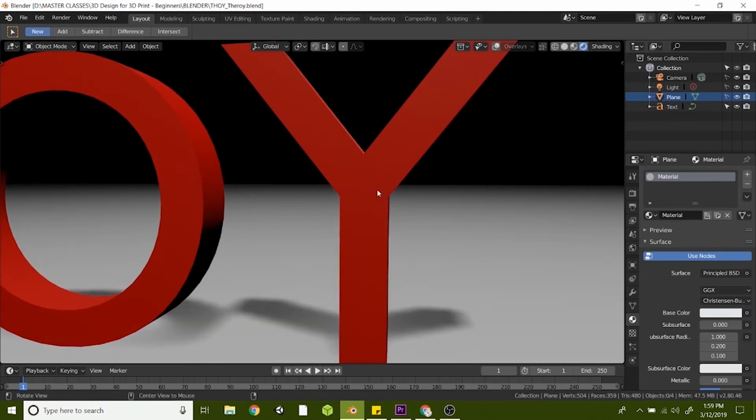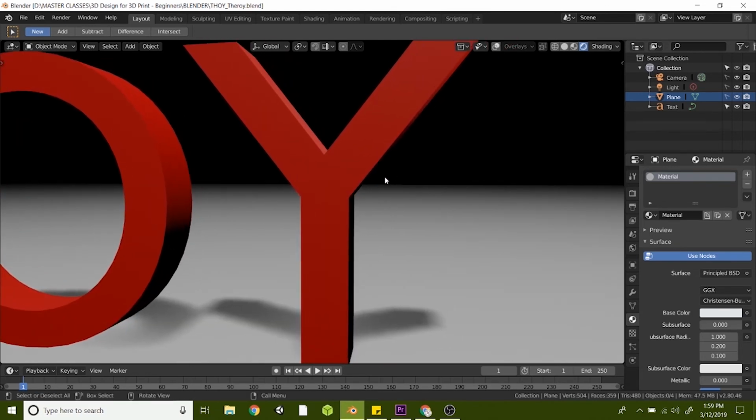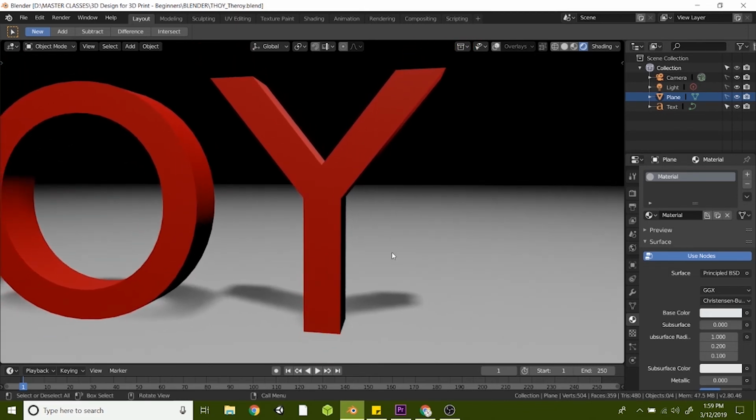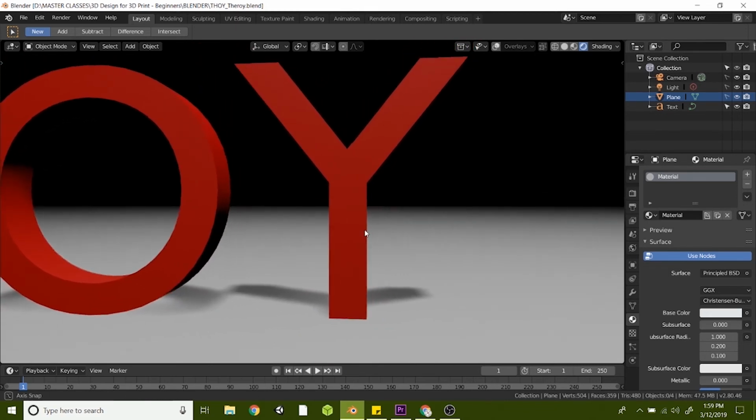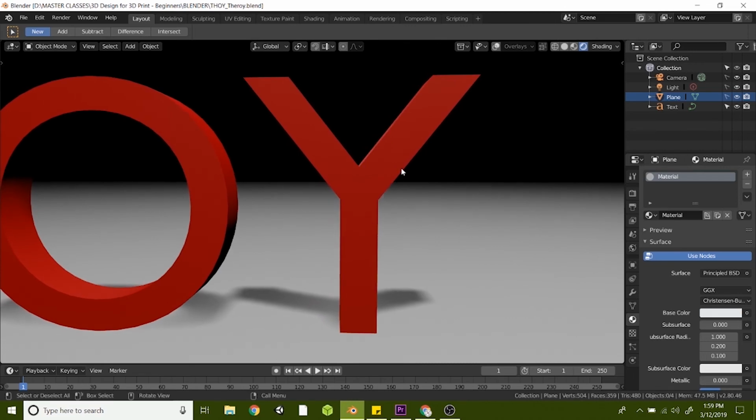I like to push a little further. Sometimes I go into 55 degrees or maybe even 60 degrees or farther. But I just wanted to keep in mind, 45 degrees is that sweet spot for supportless overhangs.